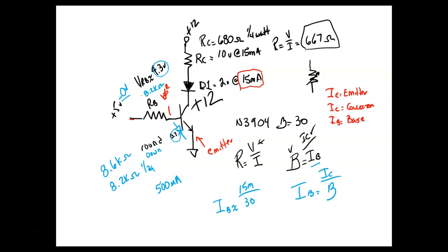So if you're looking to see if a circuit breaker's bad, I've had circuit breakers go bad, and it sets on, but when you measure across it, it's dropping 120 volts. So it's like something that might have like 10 milliamps off. No, we're not even using amps. What I'm saying is an open element in a series circuit drops the entire voltage. So a fuse could be rated at 1,000 amps.